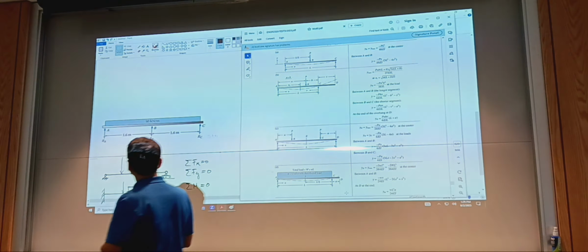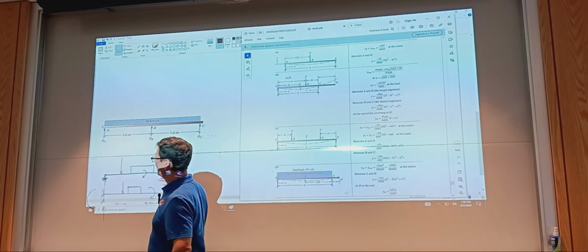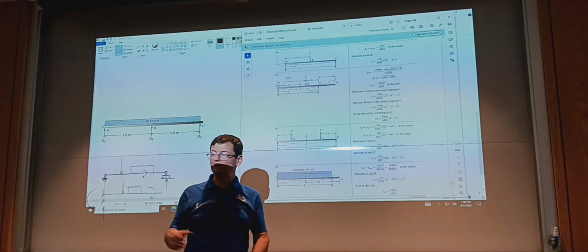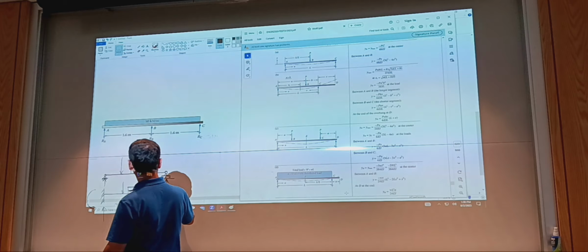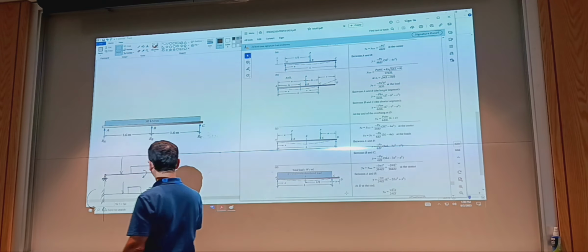Now, here it says load just from above. We have just vertical loads. So there will be 2 unknowns. Here we have a force and the moment. Here we have force and force. So really, stating equilibrium equations, you can solve for the unknowns. But for the cantilever, if I add a support here, a sliding support, then this comes in with an additional unknown, so I have 1, 2, and the third unknown.